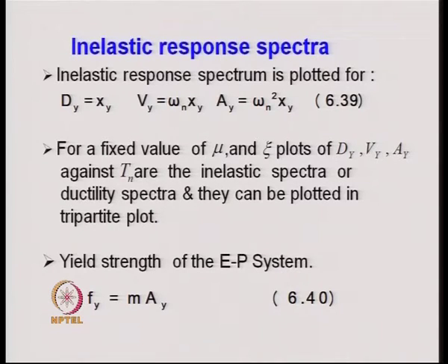So, the plot of these quantities can be made against Tn, and that would give us the inelastic response spectrum. We can see that because of the relationship that holds between dy, vy and ay, they can be plotted in a tripartite plot like the elastic response spectrum.